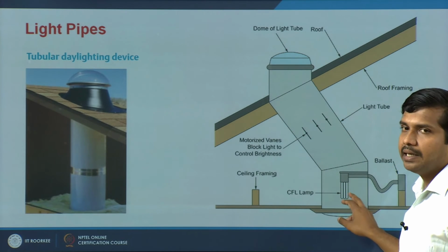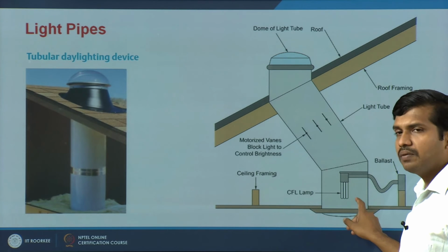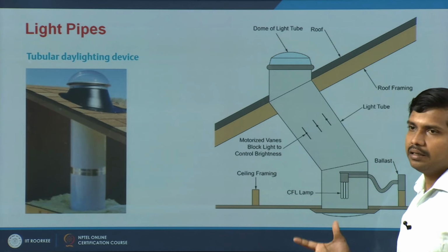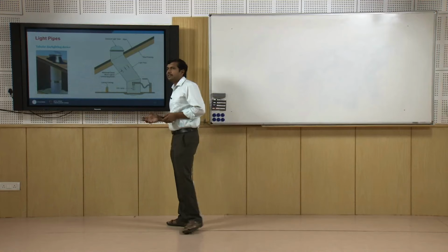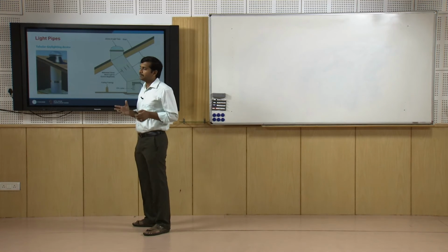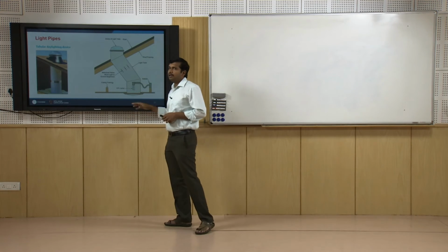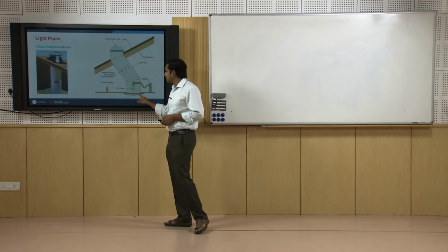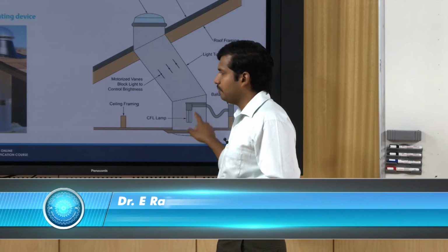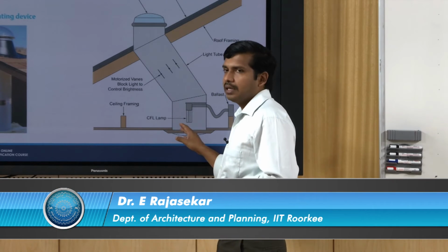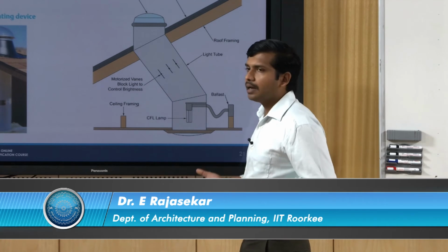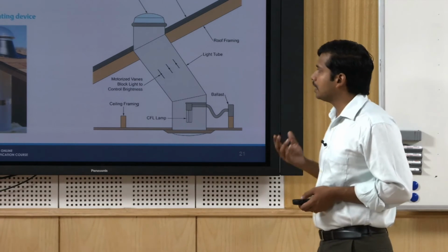For this supplementary lighting, there will be a sensor which measures the amount of light which is getting through. If the light levels are lesser, this will be actuated, this light will supplement the amount, so that the interior does not suddenly turn darker and you do not lose vision. For example, you have a basement parking, you definitely need a specific set of backup lights. There should be a sensor and actuator mechanism which will sense the amount of light coming in and actuate the artificial light. So whenever there is a lesser amount of light received, this will get activated and you will have artificial light, so interior light levels or lux levels do not get drastically affected.